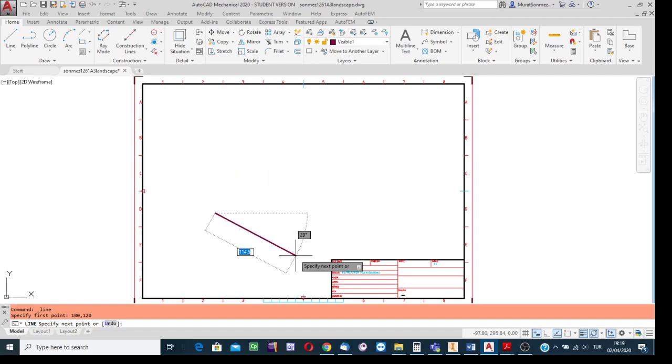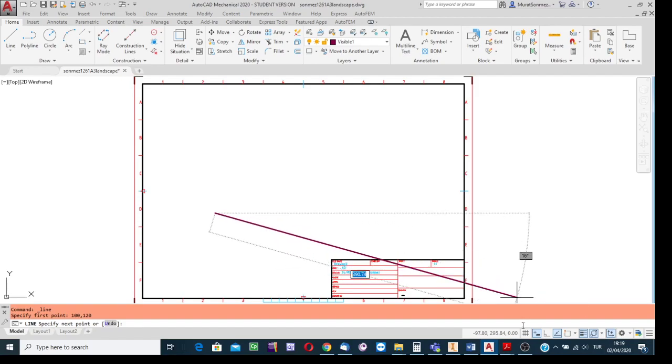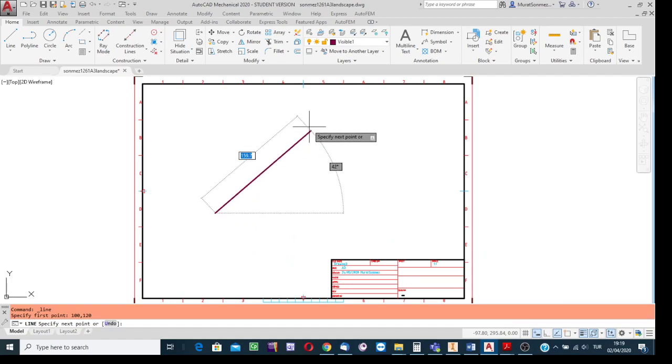If it is simulated like this, then write the angle again to its absolute value, but as measured in the clockwise direction. But always write the number as positive if the dynamic input facility is on. See the dotted circle arc and then accordingly calculate the inclination angle and write it.